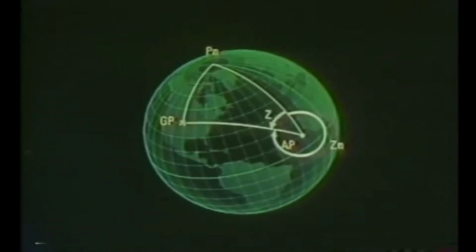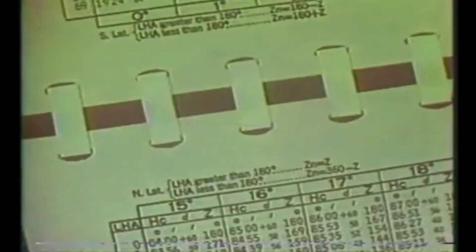A reminder for converting Z to ZN is found in the upper and lower left-hand corners of each page in the HO 249 tables. If true azimuth were plotted on a chart, you would have a line running from your AP toward the GP of the celestial body, with a segment of the circle of equal altitude perpendicular to it through the AP. This segment is represented by a straight line because the radius of the circle is so great. With ZN, or true azimuth, you can now begin to locate your actual line of position.